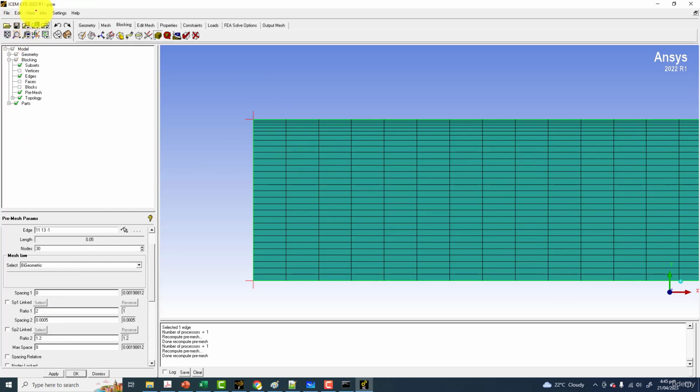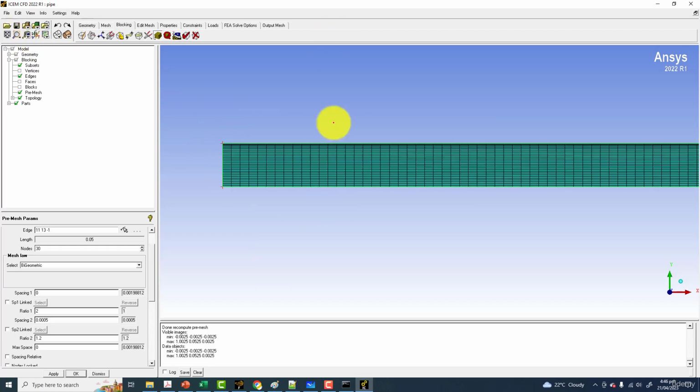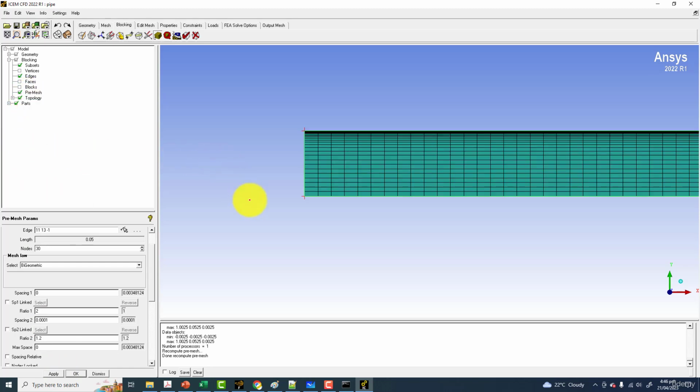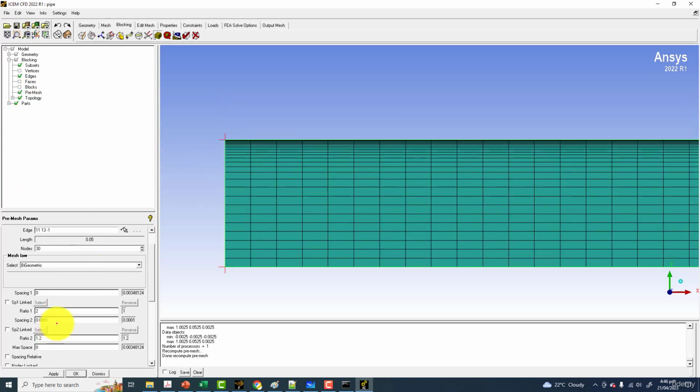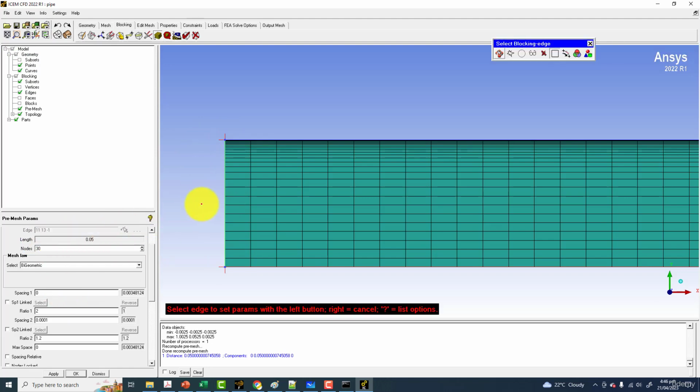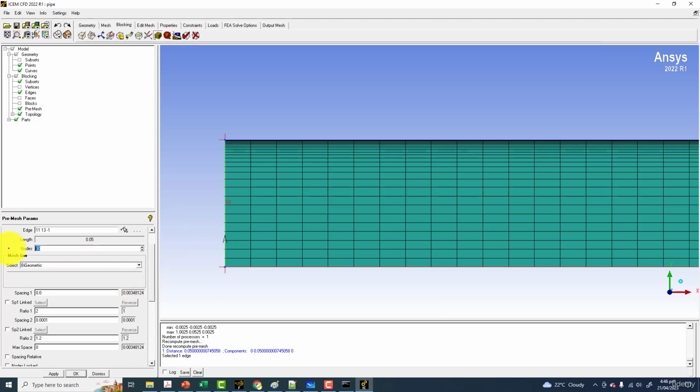Okay, so I think this spacing will not be enough. I am going to have the spacing at 0.301 and right click and recompute. Okay, this seems like, okay, let me check the geometry size. So the geometry size, the radius should be 0.05. This is okay. So let me do it again. Maybe we can make the number of cells 40.